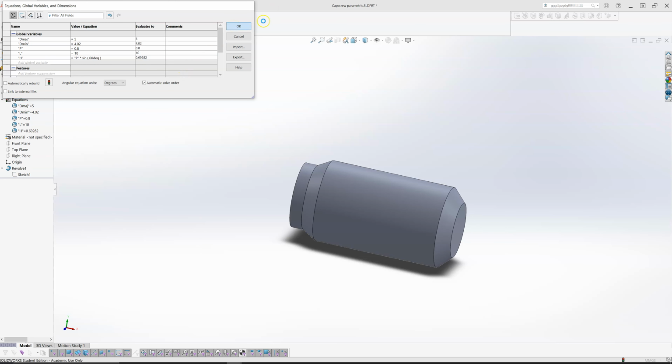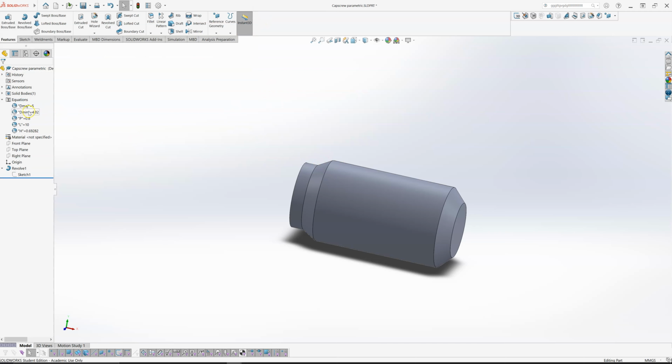And that's that. So we could have actually used that in the previous example. We could have worked out the minor diameter here by taking the major diameter and subtracting 5/8 H off the radius, so double that. If you did twice 5/8 H subtracted away from 5, I believe that should give you 4.02. Okay, so we may or may not use that value here, but it's no harm to have it in there.